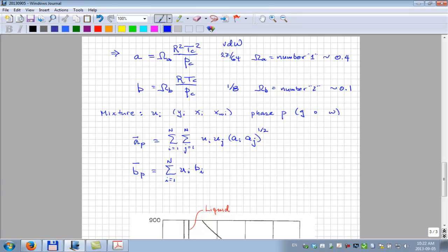So you can take a gas composition like we looked at for Troll, throw in the gas compositions, and find A and B for methane, ethane, propane, because we know the Pc and Tc of each of those, and then you can come up with the A and B for the Troll gas. So it's relatively simple.